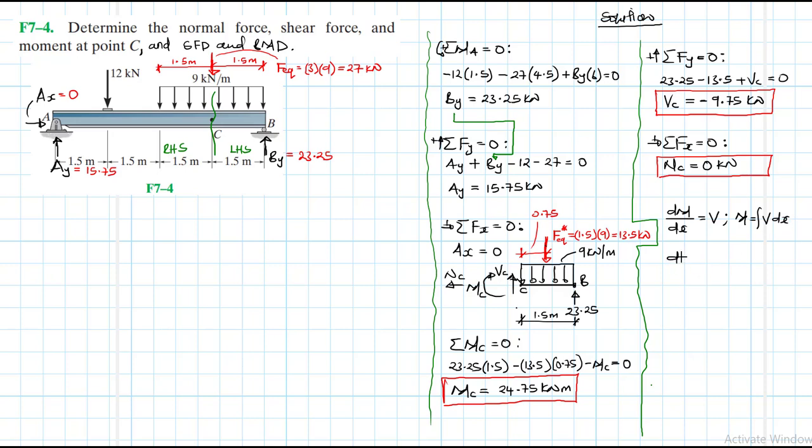And we know also that the rate of change of shear with respect to x gives us the loading, which is the distributed loading, and therefore shear itself is the area under the loading diagram. With these two equations, we are going to draw the shear force and the bending moment diagram. Great. So let's start the work.